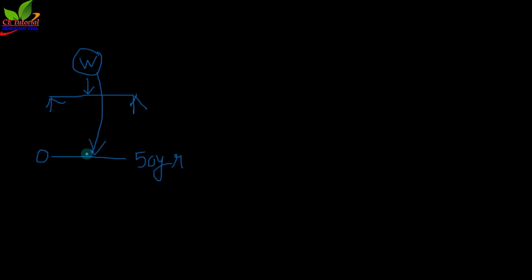So it will not exceed W. But when we are going to design according to the limit state method, we have to consider that this W is actually multiplied by 1.5 if it is a dead load.